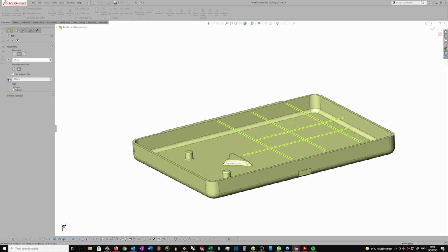So that's not what I want to do. And the moment I click on the draft button, you'll see some alternatives appear above it. So I'm going to put in a draft of 0.5, and then go back to the width of the rib thickness, and here I can determine what my rib will be at root.